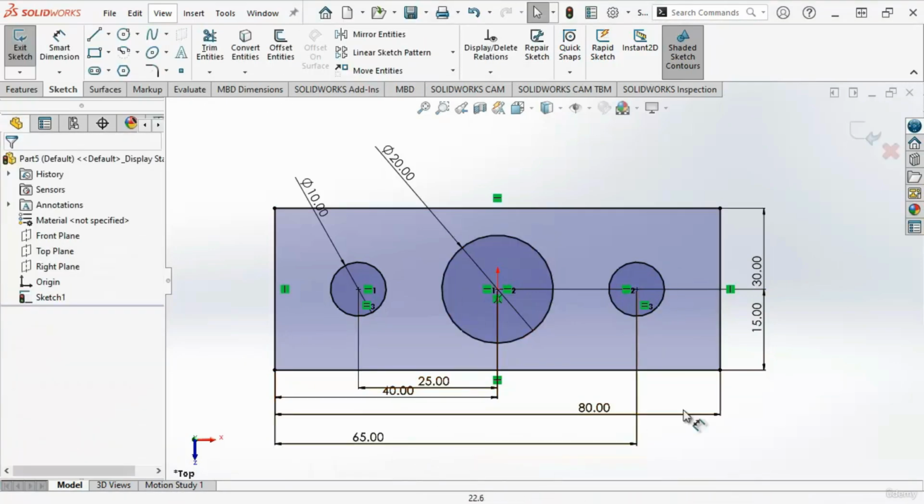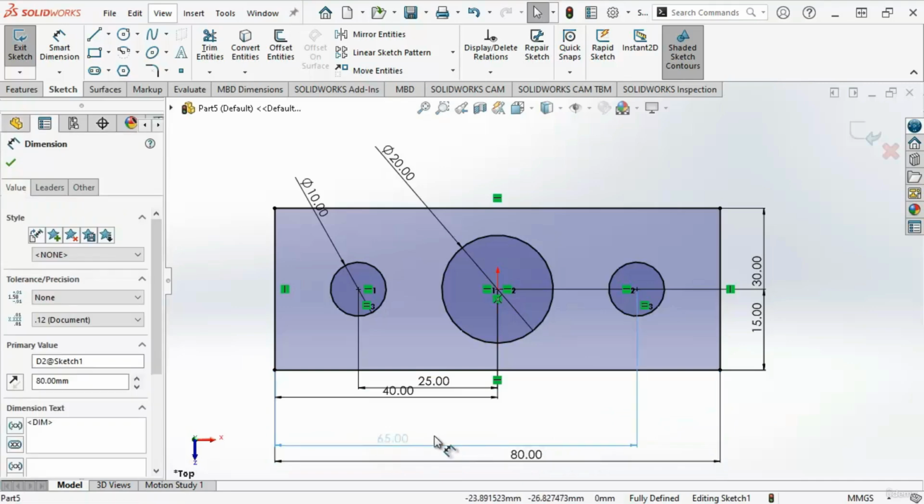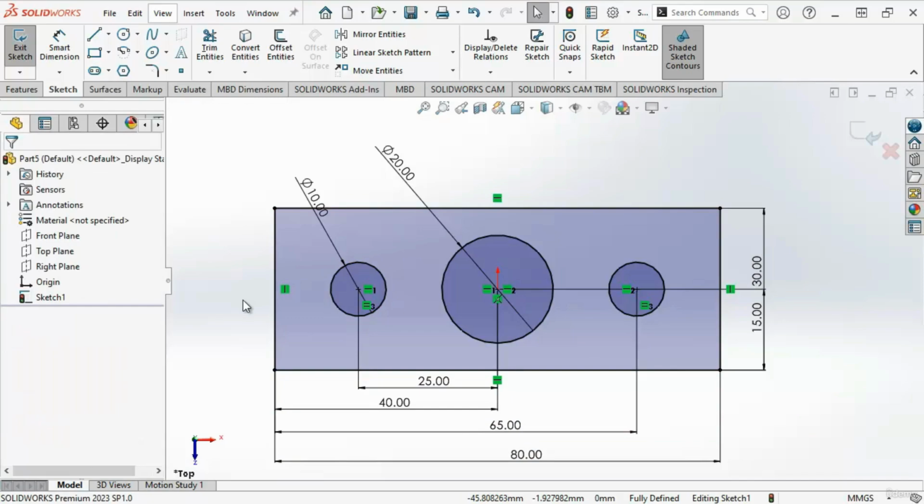Here the placement of these dimensions is not important. It's not going to reflect in your drawing, that is in drafting drawing. Because for drafting we have a separate module, you can decide which dimensions you want in which alignment. But for sketch, there is no issue with dimension. You can keep it anywhere. I would suggest if you keep it stacked up like this, maybe here, this we can put it here and here. So you will have a clear idea on which dimensions are imparted to which objects. It is very important. And with this, if you see, we have completed the example.